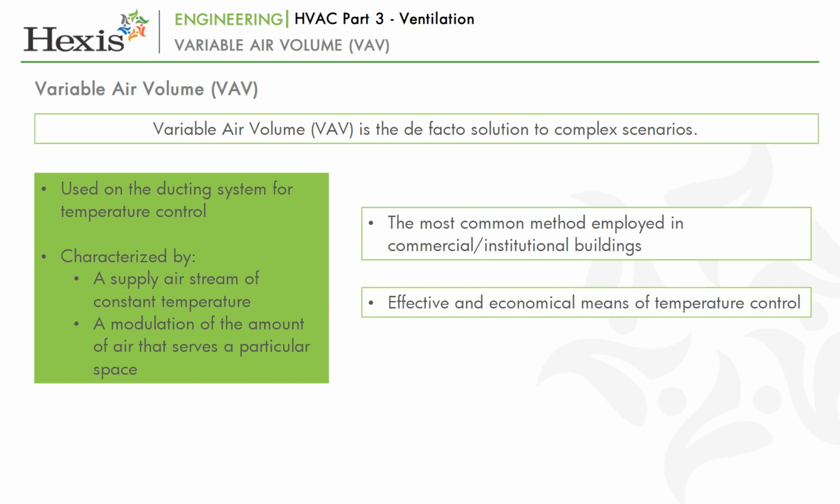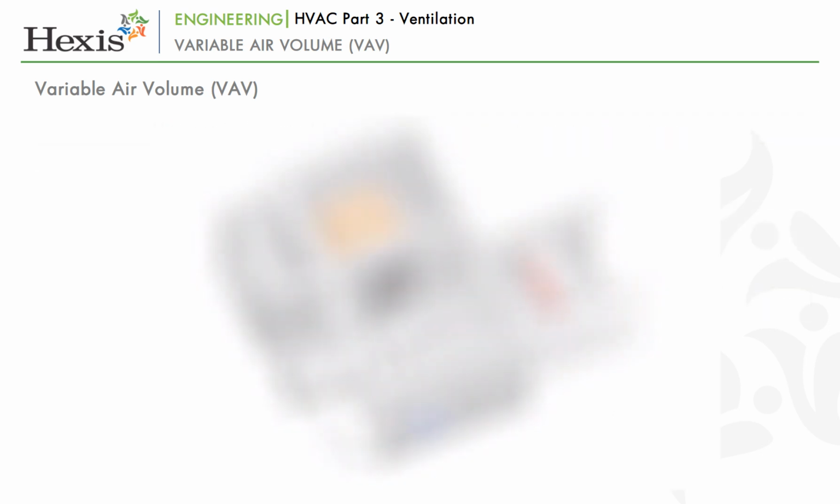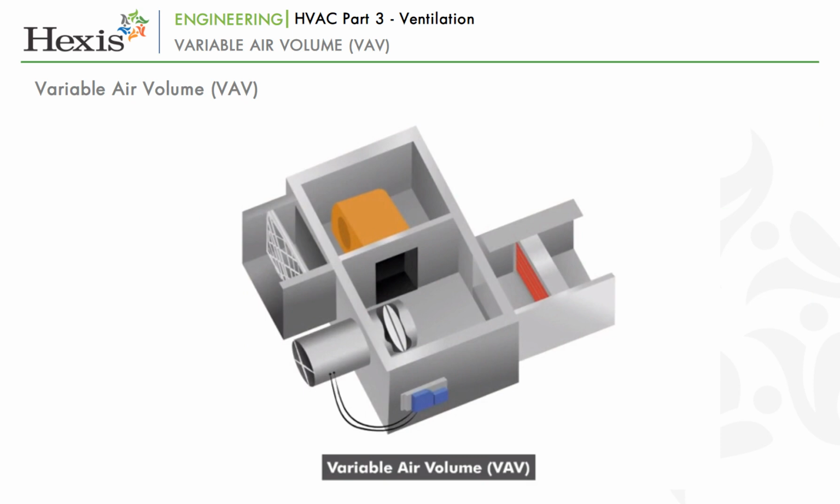However, please note that VAVs control the flow of volume of air, and hence it is important that the AHU motor is also of variable speed in order to maintain the pressures in different zones. The simplest VAV system controls air from a single supply duct and varies the airflow to each zone or room based upon the temperature in the room.